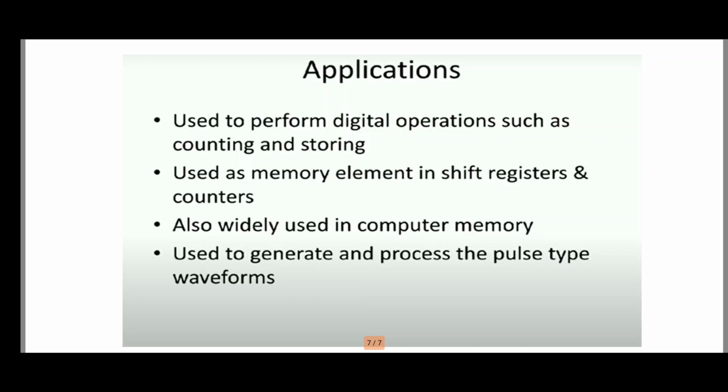Applications of the bistable multivibrator: it is used to perform digital operations such as counting and storing. It is used as memory elements in shift registers and counters. It is also used in computer memory, and this kind of bistable multivibrator is used to generate and process pulse type waveforms. And overall, the bistable multivibrator is also called a flip-flop circuit.